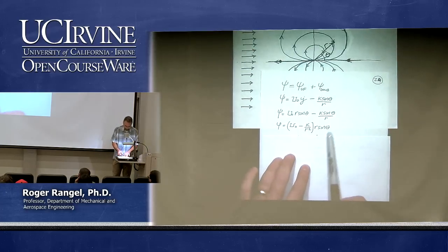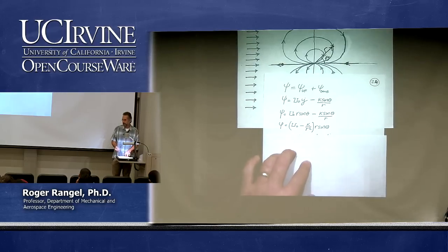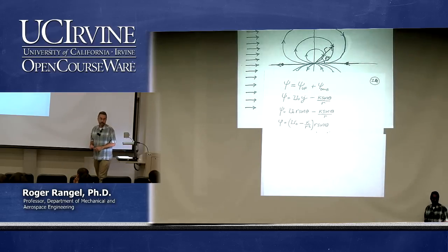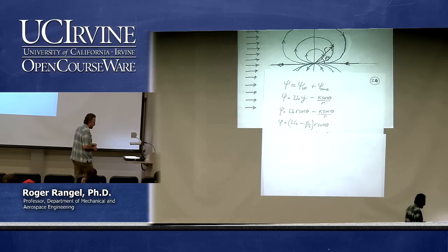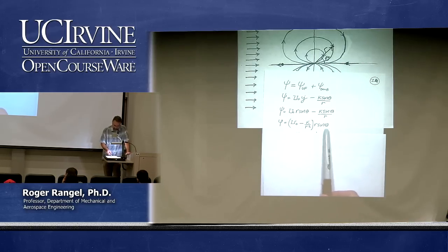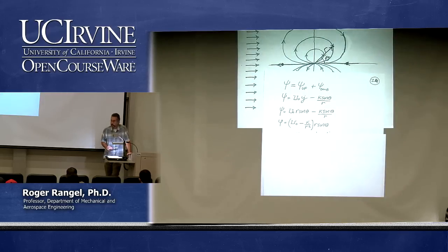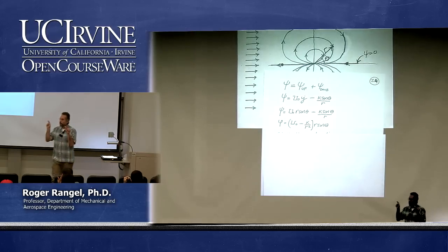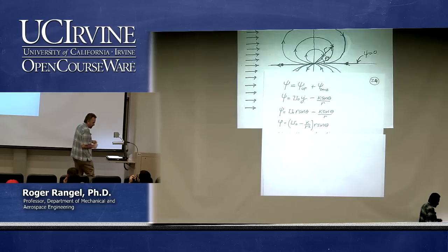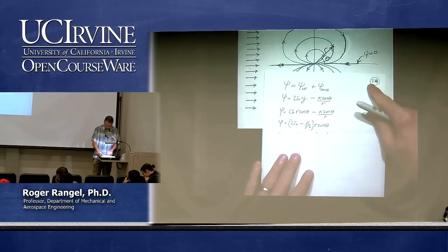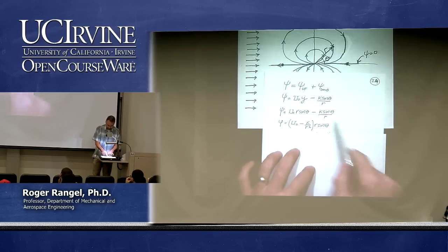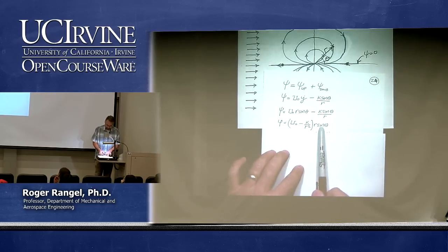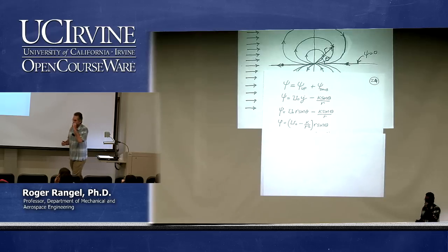So in either case, if theta is equal to 0 or theta is equal to pi, the sine of theta is 0. So we, just from looking at this expression, can conclude that the whole x-axis is a streamline, because it has the same value of psi, which in fact is 0. Because if I put theta equals 0 or theta equals pi, I cover the entire x-axis and I get psi equals 0. So we just figured out that this line is psi equals 0. So therefore, my two stagnation points are on the streamline corresponding to psi equal to 0. But what happens is that this expression here has another way to be equal to 0. Right? I can pick theta equals 0 or theta equals pi, and that gives me 0. But I can also make the parenthesis 0. And I also get psi equals 0.